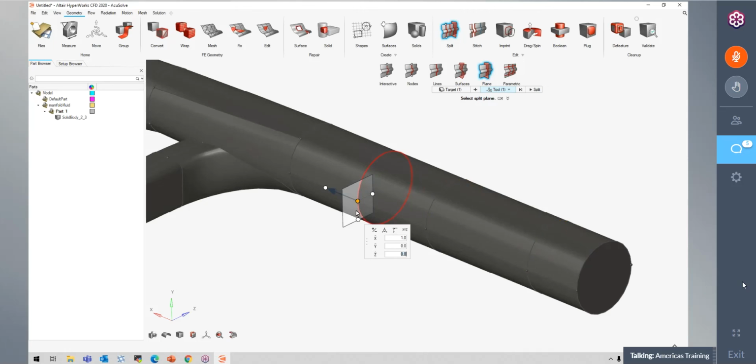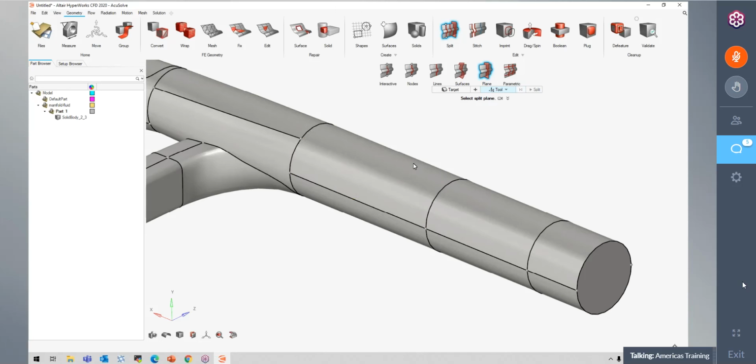And you'll see that it'll give you a preview as to where the cut will be. So right here, it's sort of telling me that it will cut across the pipe here. So it's showing me sort of the cut surface there. If I click on this back arrow here, this triangle with a little line on it, this will deselect what I just chose. So it'll clear my selection if I want to try something different. So if I click on that and I see that the cut's not what I wanted, I can clear my selection using that button there.